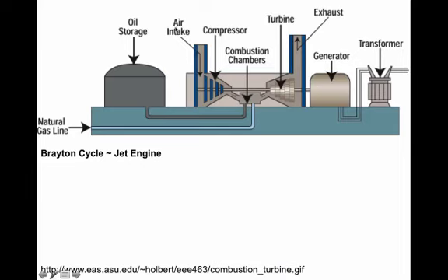What we have is an air intake here, we compress it. Under high pressure here, we add either oil or natural gas. Then it burns and expands out the exhaust. And so because you heat it here, you're pumping way more volume of gas out than came in because the gas expands. Now, the efficiency limitation in a Brayton cycle, in a jet engine, is there's still a lot of heat in that exhaust.